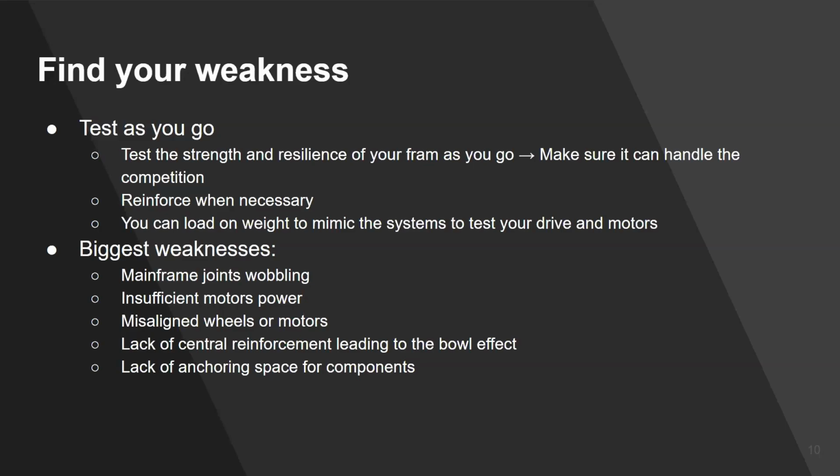Make sure that your motors are sufficient. So like I said, test them out, adding weight to your system and testing your drive. See if your motors have enough juice. And if they don't, switch them out early, especially if they're in a harder to reach location because of the design that you made for your robot. The less you have to switch out your motors, the better it'll be for you.